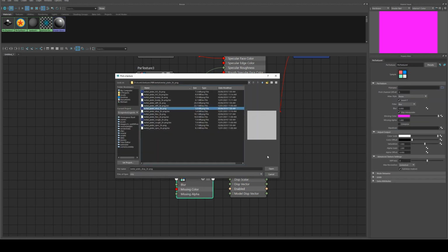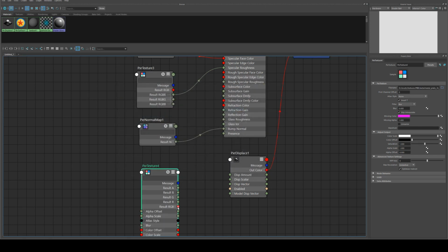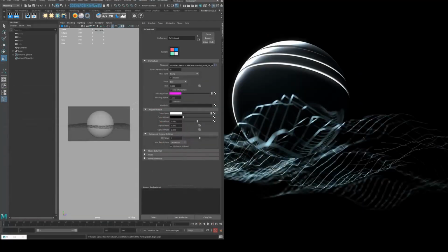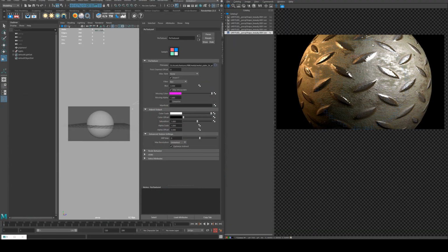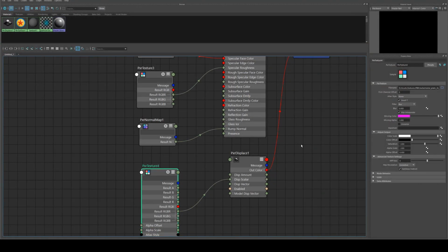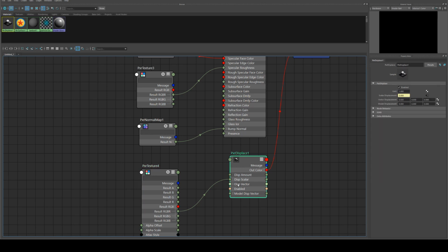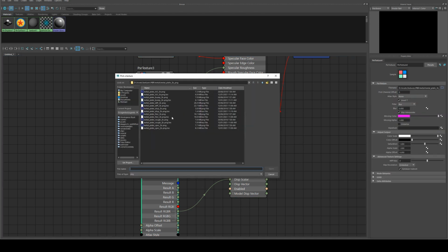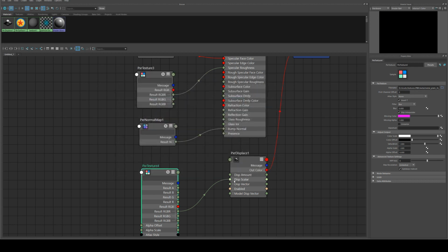Now the interesting thing about this map that I noticed, and this is worth noting just in case you run into a similar thing, is it's completely grayscale and is actually not a displacement map. You'll see it's displaced everything evenly, however it's not actually displaced anything differently from another. We still have an even surface around the edge. All it has done is made it bigger, and that's because it's displacing everything by a value of 0.5, and we're using scalar rather than vector because I would have assumed that this map should have a vector displacement, but it doesn't. So what you need to look out for here is if for some reason your map doesn't work, but you did actually get a bump input, you could use that instead with your scalar input.